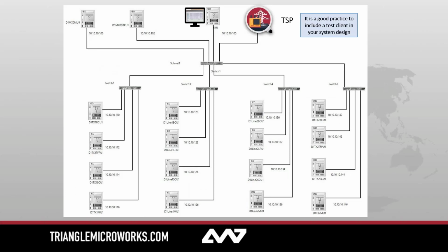This slide shows the overview of the substation with the different IEDs that we have in the base. So we see that we have in each of the bays basically 4 IEDs, a bay control unit, a protection unit, either the line protection or the transformer protection unit. We also assume that we have a fully digital substation with switch control units and with merging units in each